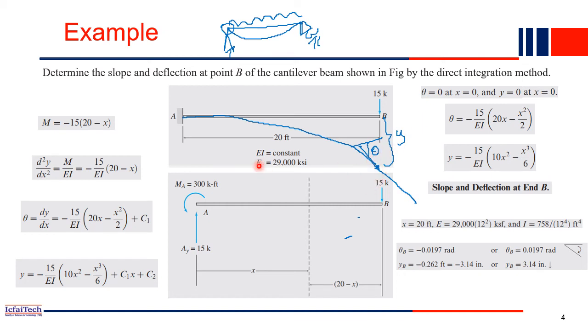So our first step is over, that is drawing the elastic curve. Our next step will be to write the moment equation. Let's do it quickly. How can you do that? Let's consider our variable x started from A. Let me do it here. Our variable x starts from the support itself. So from here you have the x, right?